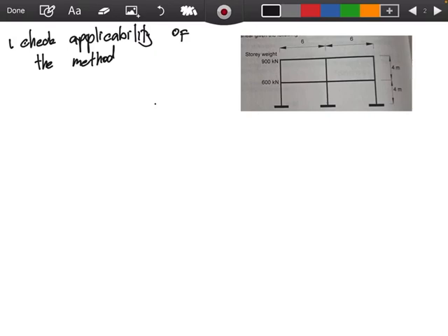In our NSCP, is it in the part where it is buildings of any occupancy not more than 3 stories in height that use light frame construction? This does not use light frame construction, but it is under the category of other buildings not more than 2 stories.